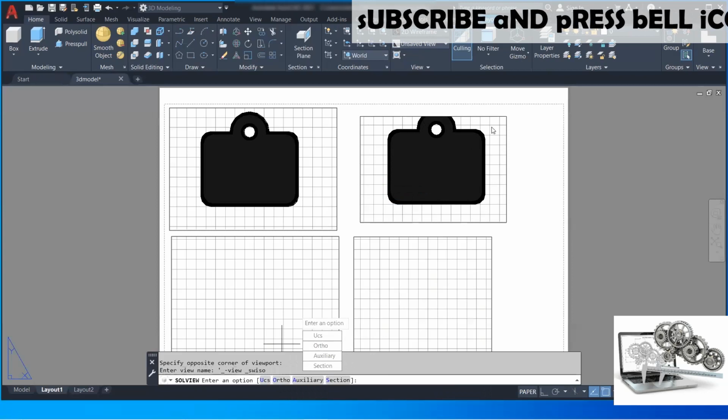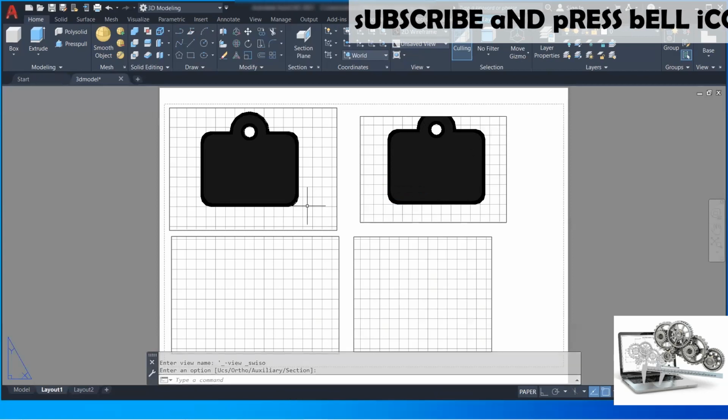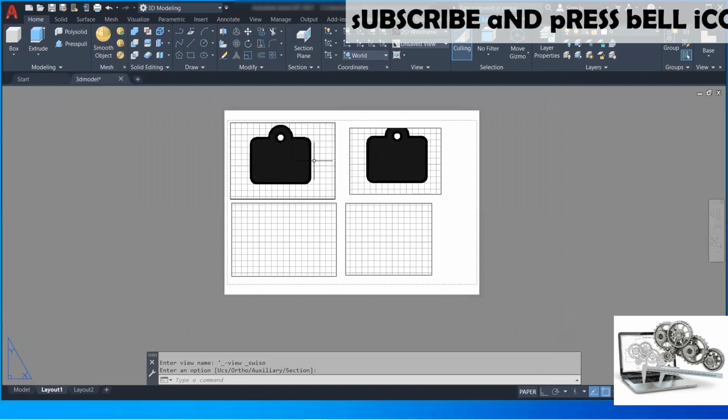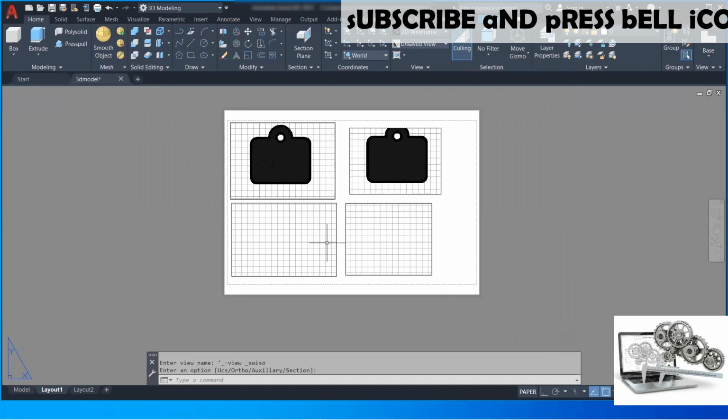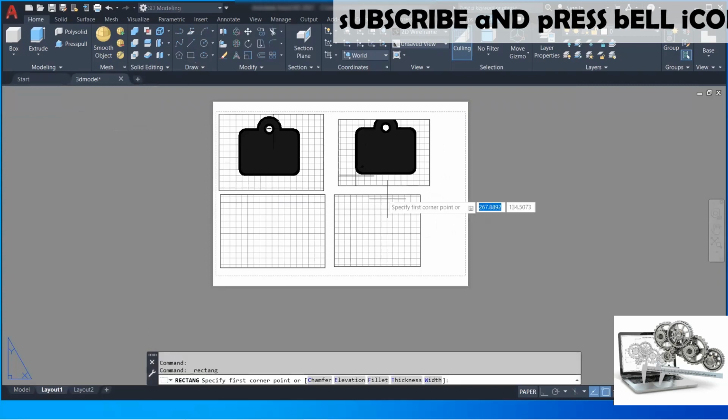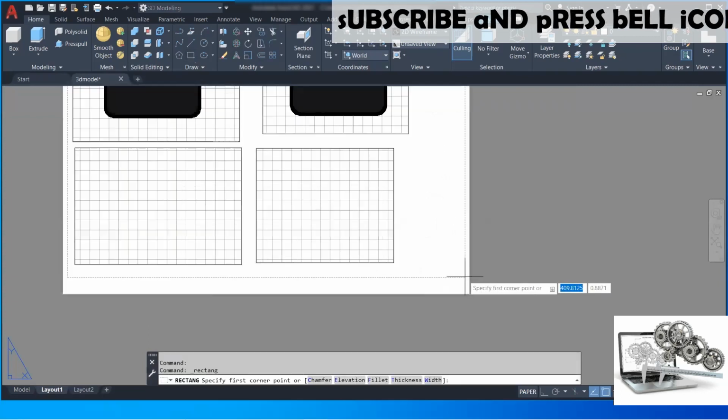Okay, now we have to set the viewports according to our requirement in height, width and the visualization. First select one viewport and change its height and width in the property manager.